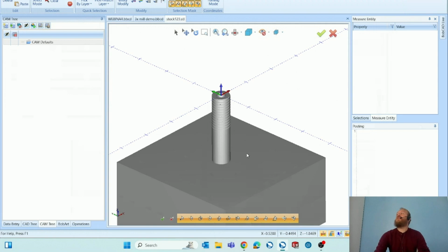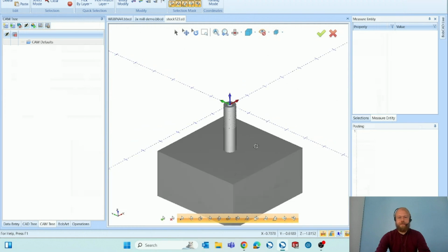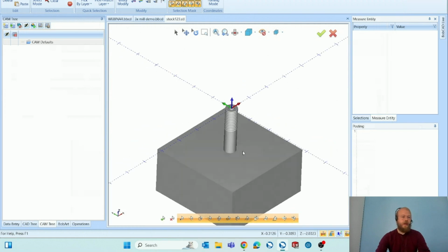I found a free software program called FreeCAD. You can download it and actually import an STL file and convert it to a step file to make more adjustments after the fact. So that's kind of an off-topic thing about STL files. If you wanted to create a thread, change it to a step file, then change anything else about the part file, you could do that.